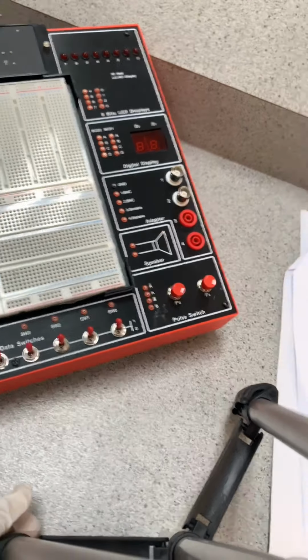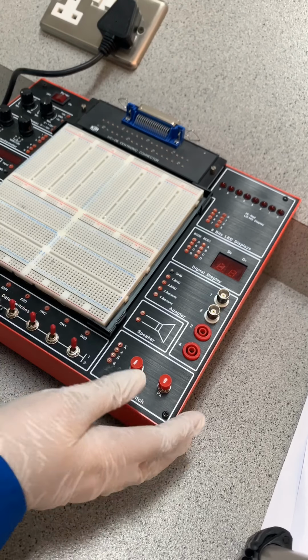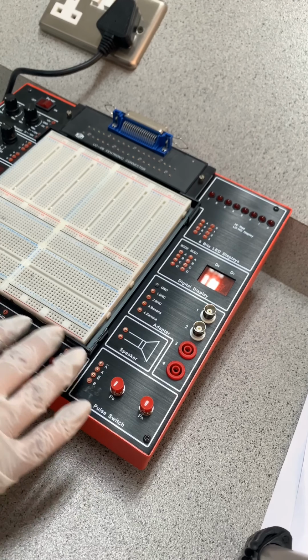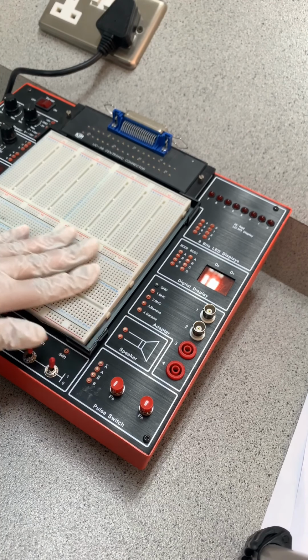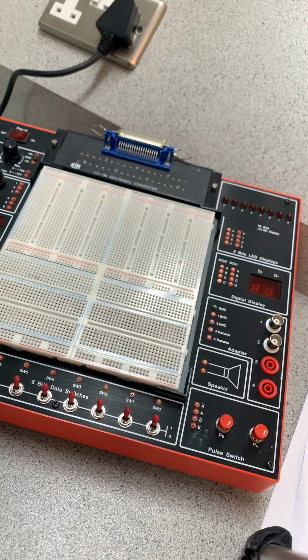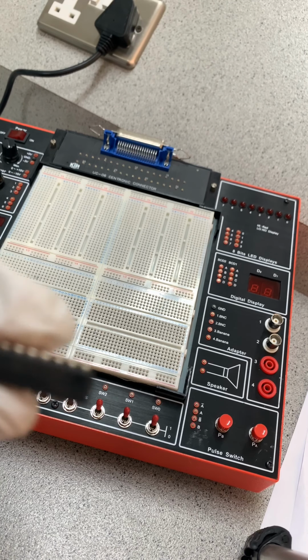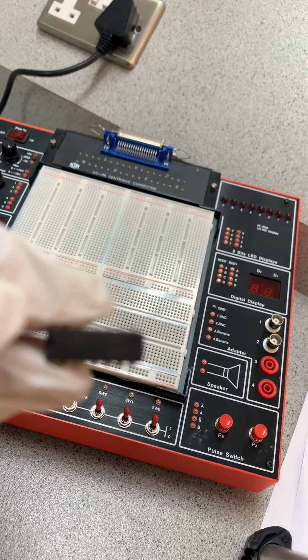Just showing to you all. So just to remind you also, here is the LED, which is the output, and this is the switching dealing with the input, and here this one will be the VCC and the ground. Okay, so the breadboard will be here. So let's start connecting. First of all, I have to identify where we start connecting. From the hole, here you have the hole. From the hole I will be starting as pin number 1.